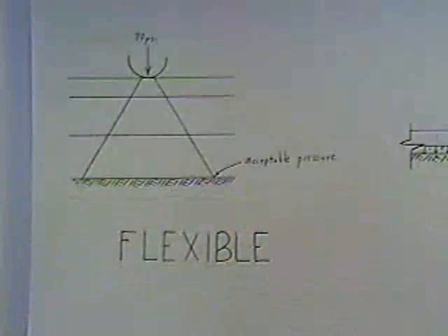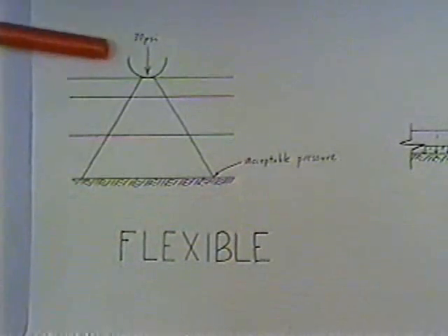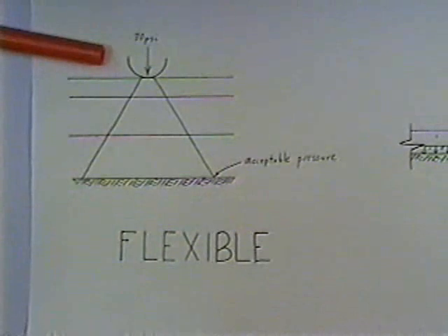The other slide that's not in your notes, again, shows the wheel loadings that we're looking at for flexible pavement, and then I'll show you a rigid pavement as well. At the top of this drawing, that semicircle represents a vehicle's tire on the pavement surface, showing 30 psi, so it's a passenger car tire.